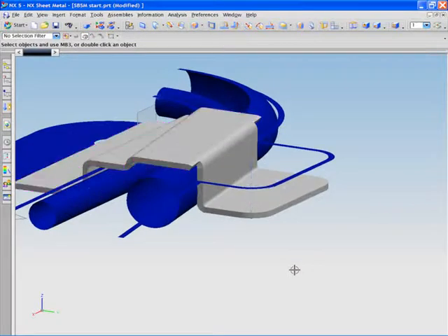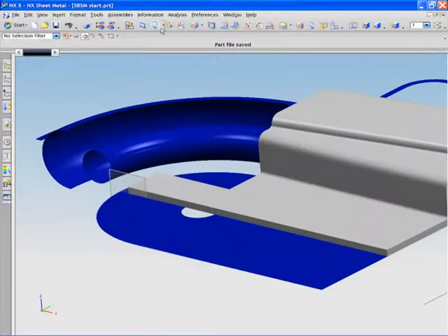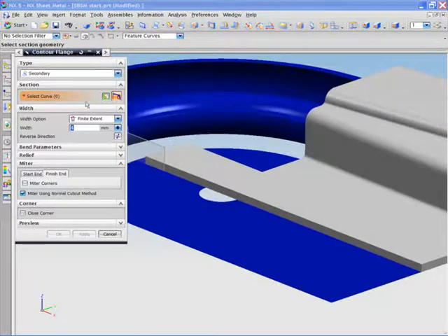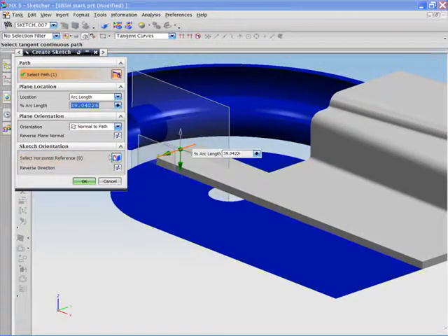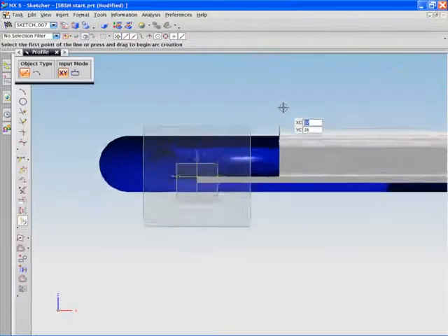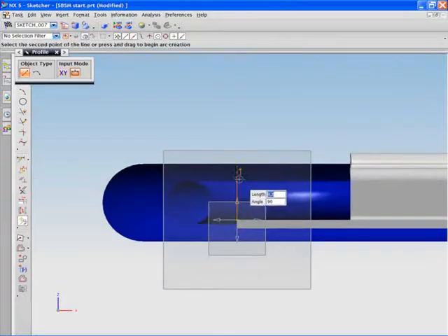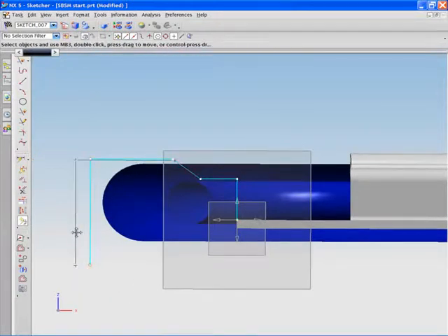There are situations when different construction techniques are required, and here you will see that the designer uses a sketched profile to create a more complex flange section easily. The designer can quickly draw the profile and then add design rules relative to the tubular frame. NX then creates the flange based upon inputs from the designer with respect to the width and type of relief.